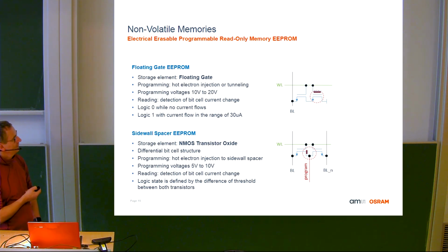And then you have to find something where you can build a capacitance with this floating poly, just to introduce, or let's say, couple a voltage here. And if you would use the second terminal on a metal, which is typical in the flow, you have the poly, then you have the metal. You could also build a coupling.